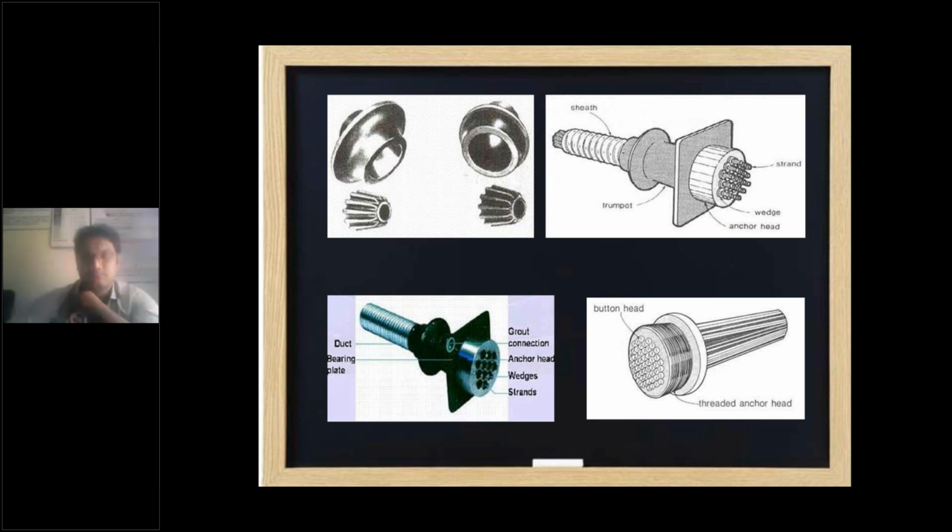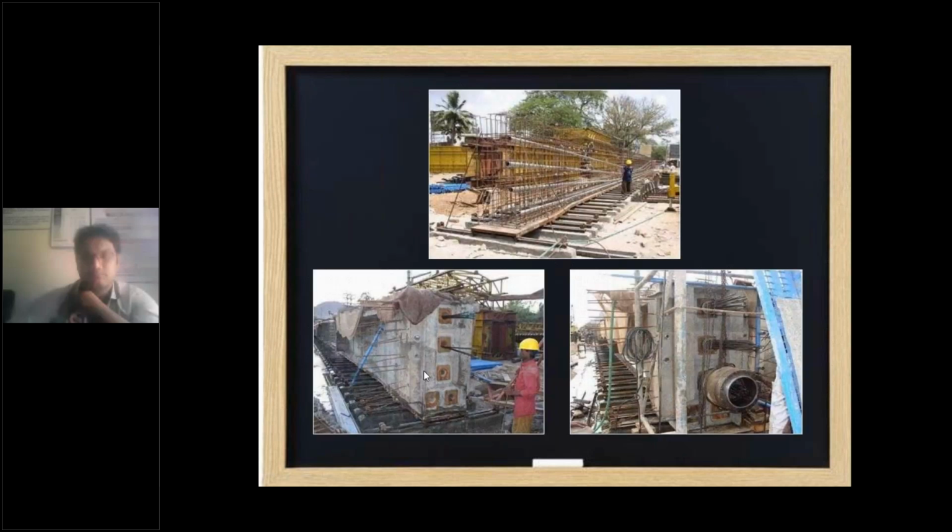So this is called a girder. After casting it will be like this, before casting. See how the duct was placed within the reinforcement. There are 4 different stages where the sheathing or duct is provided, in a parabolic shape. So it is not straight, they are all in a parabolic shape. Why parabola? Everything we will come to know in the design.